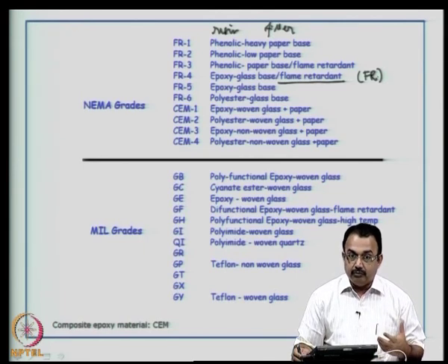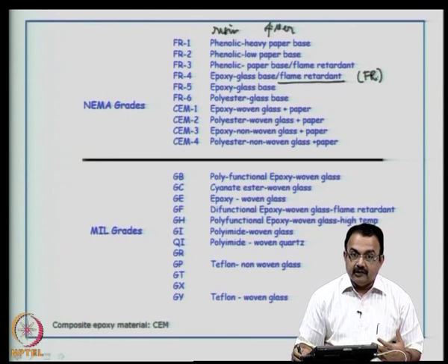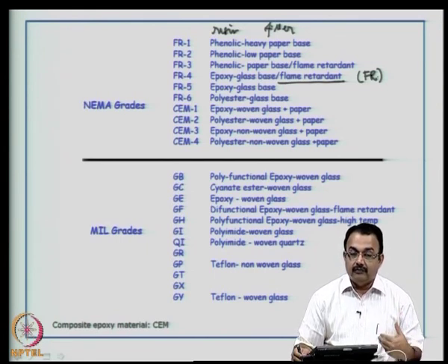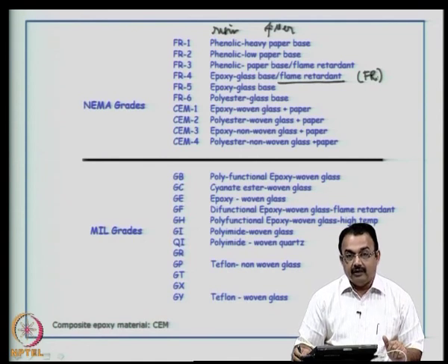So, when equipment using a PCB of FR4 or FR5 qualification is used, and if there is some kind of over voltage or short circuit in the equipment, then the PCB, being organic, can catch fire, or because of the fumes that emanate when the temperatures exceed certain limits, it can catch fire, but it should have the ability to retard the flame by itself. That means, it should have a self extinguishing property.